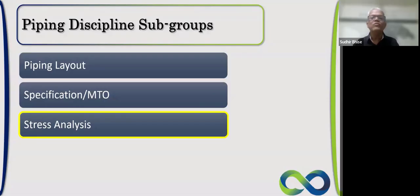Now, why stress analysis is required is that many of these lines, out of these 1,000 or 10,000 lines, will need special attention in designing. How to identify those lines and how to design them is taken care of by the group handling the stress analysis. If a plant contains 10,000 lines, you need not give the entire attention to all of them. Some piping will need a higher amount of attention in design, some a moderate, and some a low amount.